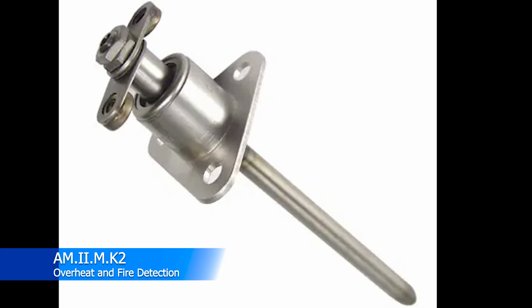Okay, so this is a thermal switch that is used on Honda jets and a couple other aircraft. You notice you have a probe that's stuck out on the end, and then that triangular bracket that has three holes in it. That's because it's going to mount to wherever that probe is going to stick into. So you'll find these on inlet areas, or maybe even inside of oil reservoirs or whatever. Any place that fire may be likely, that's where they're going to be placed.